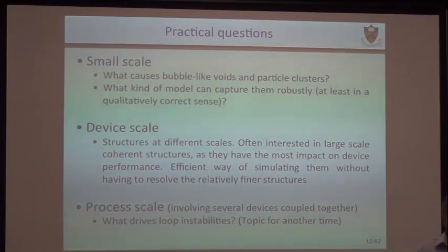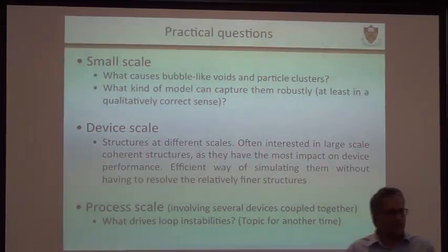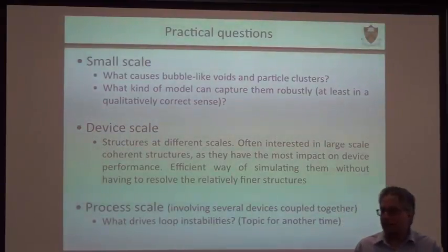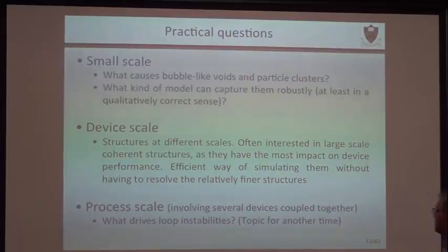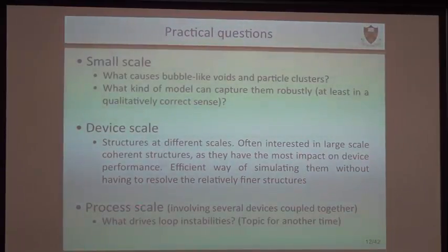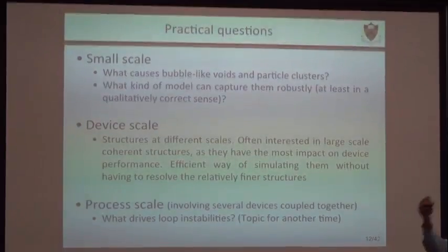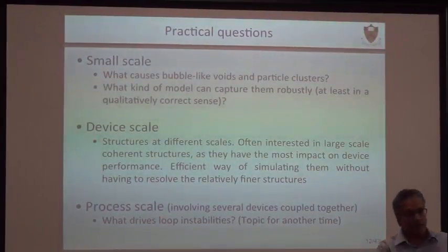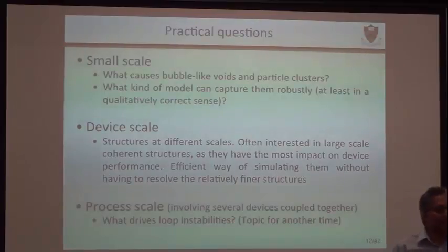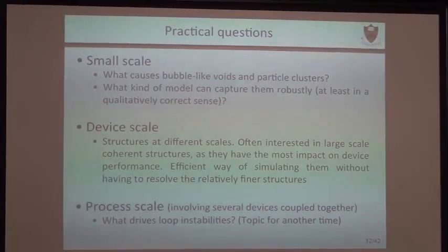So those of you who have already simulated turbulence can see it's not very different from the same question that we ask conceptually. But when solids are being handled, often solids from one vessel go to another vessel, you do something else to them, and you recycle them back. So there's a circulation loop, and you can get instabilities associated with the coupling between them.